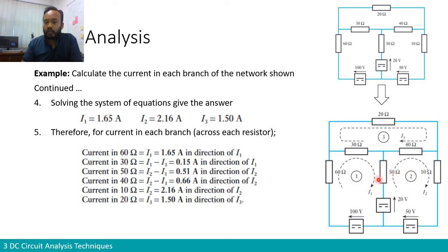But of course, what's going to change later is the sign in your equation, and you will fall back on the same answer at the end. Just make sure that you follow the direction that you have assigned. But to standardize and make it easier for you not to become confused, I strongly suggest you always select the same direction of current, for example clockwise.